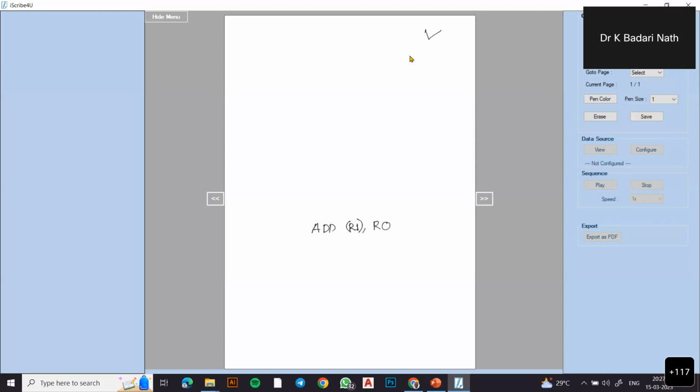Now, let's say this is the instruction. Now I have some value available in the R0 register, some 20 is available. Now I want to add the contents of R0 to a memory location. Now, the memory location is not directly specified in the program, but it is specified through some other means. What are the means? R1 is used here. So whenever I use the instruction like add R1, R0, what is the meaning of it? I'm adding the contents of R1 to the R0 directly.